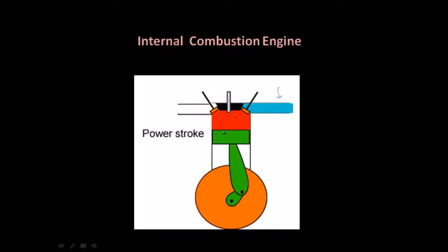Then the piston goes up as the shaft continues to rotate, and that compresses the fuel and air. And at that point, once it's past being at its maximum height so that the shaft is a little bit bent over this way again, the spark plug ignites and there's an explosion, and that explosion causes a tremendous amount of heat energy to be converted into mechanical energy by pushing hard down on this piston, causing the shaft to accelerate. And then on the next upward stroke, the hot gas goes out through this valve. That's the exhaust. That's Q sub L. So let me see if I can get this thing working again.